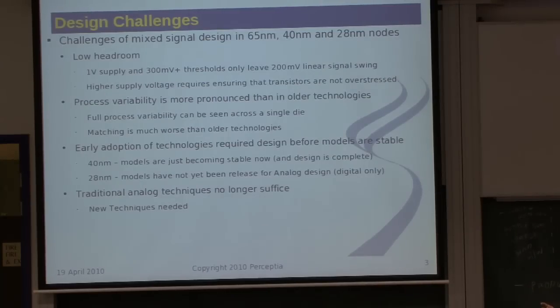Somebody's done a whole bunch of computer processing to produce the masks so that the interference pattern resulting from what they put on the mask when the light hits the wafer has feature sizes down reliably at the 28 nanometer level.